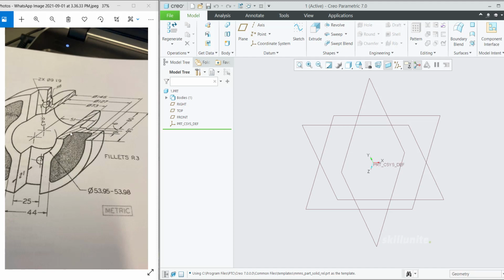First we are going to create this portion over here, this complete box-like cross section, whatever you are seeing over here, that we are going to make. Then we need to make this cutout and this cutout, so that we will do separately. Then holes, everything we can make afterwards. So just select a particular plane. Let me choose the front plane and then go to the sketch option.